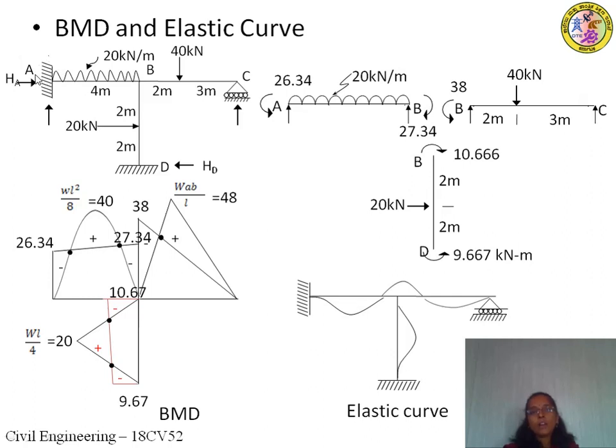Okay, if a fixed end or a hinged support is provided at the beam level, then you can take those frames as non-sway frames, and you cannot take a frame with the roller end at the beam level as a non-sway frame. Okay, because we don't have any horizontal reaction for a roller, provided the roller is supported in the vertical direction. So here the reaction is in the vertical direction. If the roller is rotated by 90 degrees, then the reaction will be in the horizontal direction. In that case, you can take that frame as non-sway frame.